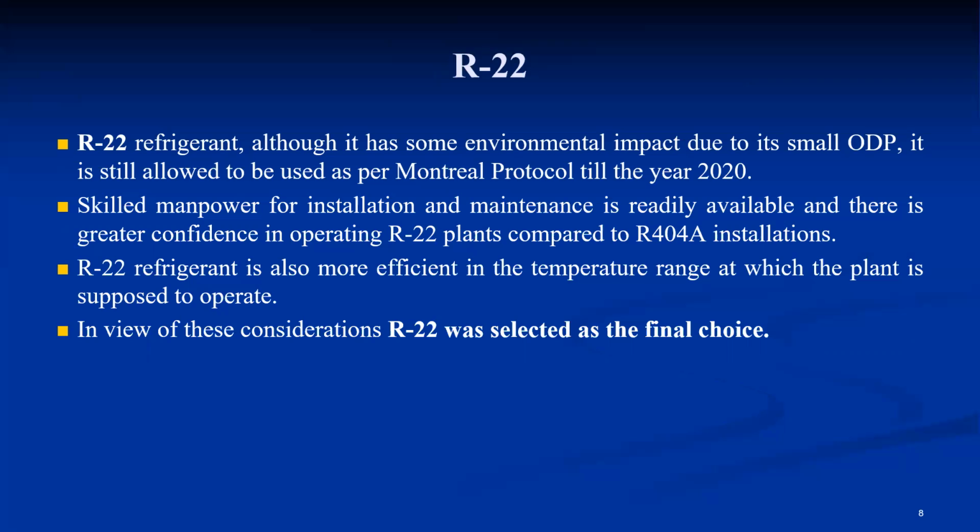So this is generally the policy of selection of a refrigerant. In most applications, some refrigerants are dominant, like ammonia is dominant in large refrigeration applications, even in cold storage also, but not preferred for storing unpacked products.